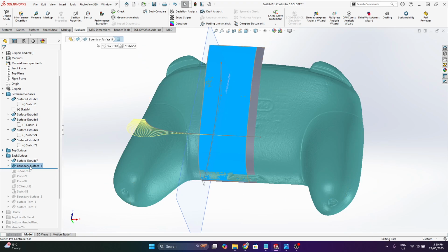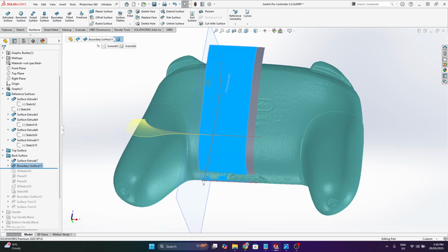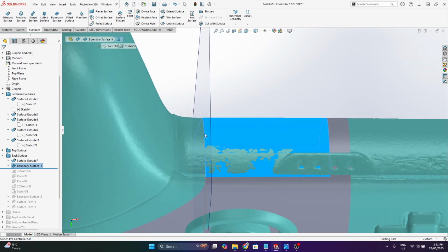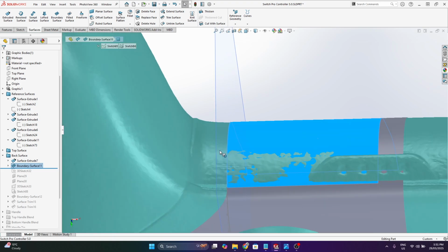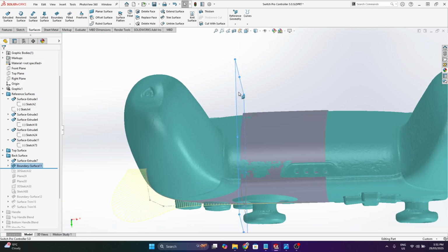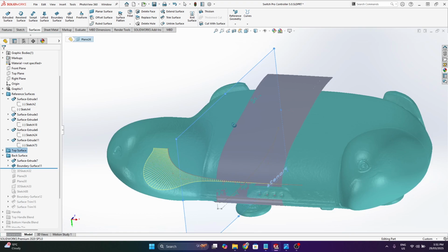By the way, in most cases here, I'm using the boundary surface tool. I guess this whole video assumes you're somewhat familiar with that tool. Another option, I like to add the surfacing ribbon up the top here. You can use the lofted surface, but boundary surface is a little bit more powerful sometimes. So here, I made a single surface up to a point where I realized the curvature starts changing quite a bit, but up until this point, represented by this plane, it's more or less flat.